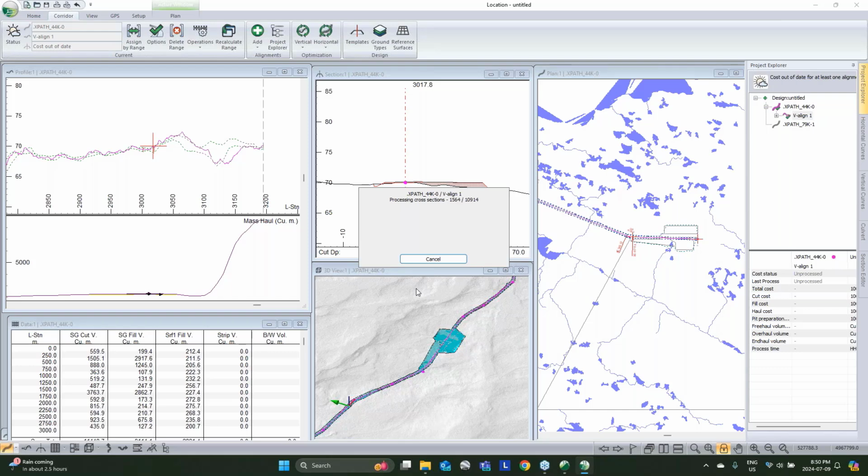And it's going to run through, do that sampling. Once the sampling's done, it's going to figure out where our curves tangent should be, what grades we should be dealing with, and what elevation everything should be at. And it's going to consider the problem as a whole, minimizing our costs, and adhering to those design constraints that we've given it.